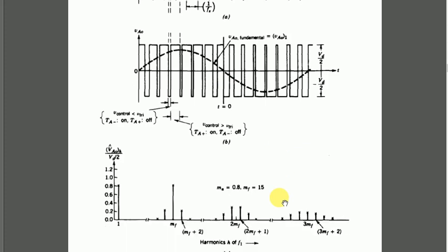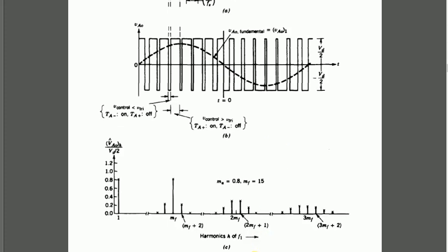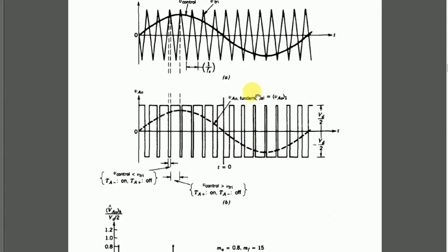Before discussing the frequency spectrum, let us focus on this square wave. This square wave, which is switching between Vd/2 and minus Vd/2, is the actual output voltage of this inverter. But if we apply some particular filtering technique, we get this dashed line, which resembles the carrier wave, and this is what we want at the output, our desired signal.